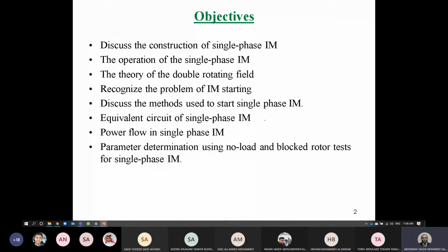Today, inshallah, we will continue our discussions on the equivalent circuit of the single-phase induction motor, and this will include the equivalent circuit at steady state. So, at steady state, Shabab, we will care about the equivalent circuit of the motor, including the main winding and auxiliary windings, or the split phase induction motor. Which means both a forward flux and a backward flux will be there.